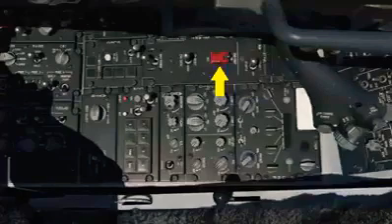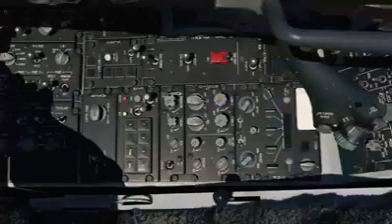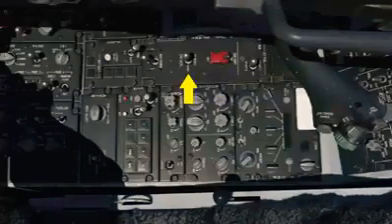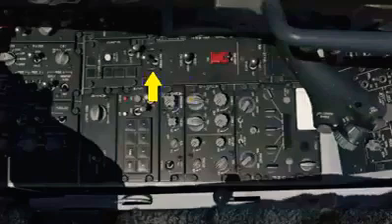Also in secondary mode, the cycle light will illuminate on the caution panel and you'll have a higher thrust at idle power. Below that is the AB reset switch, and detailed engine parameters can be recorded. The max power switch at the bottom of the panel is inoperative and not used in the 129 engine.